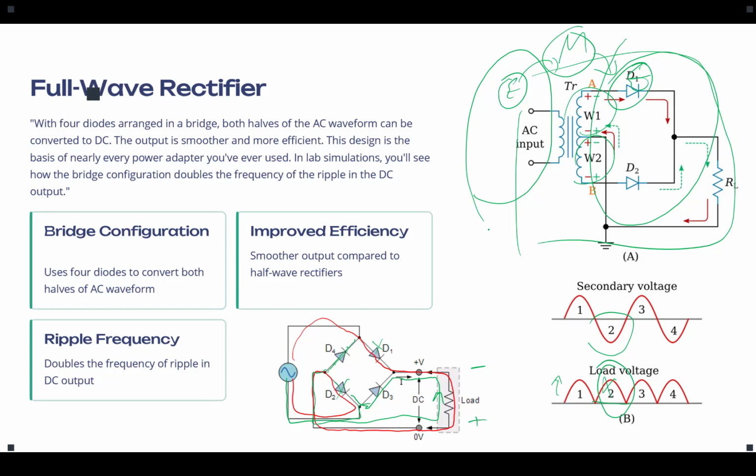Plus, as we know, the transformer is L. And in reality, the winding, the solenoid, also has an R. So we have an RL circuit, a series RL. What is the RL circuit in series called? What does a series RL circuit do for you? It's a filter, a low pass filter. So it would also eliminate the noises.